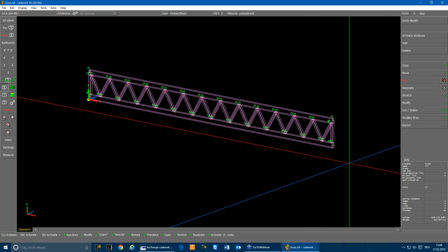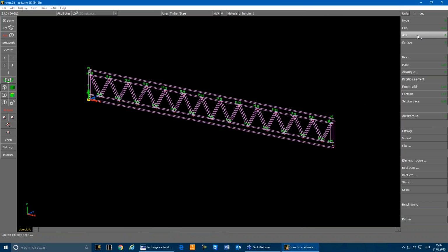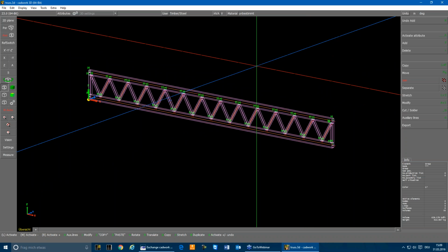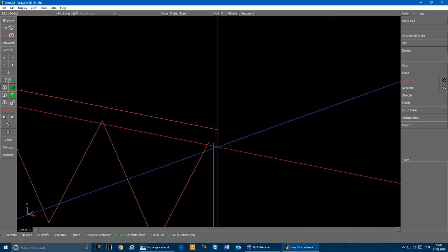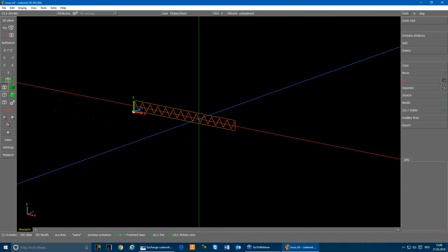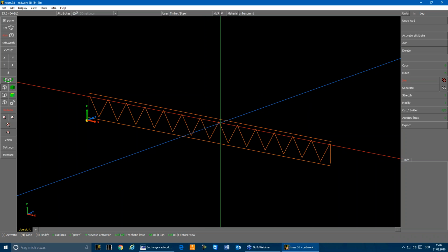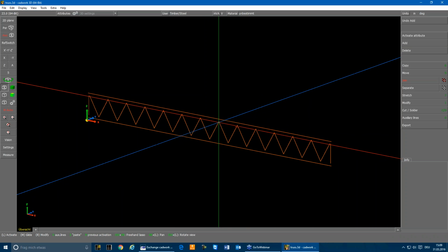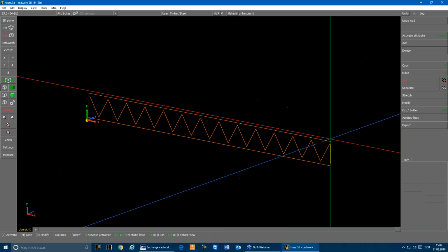The first option is that I will activate all the beams, and I will go to Add Axis and define the system axis for each beam. That means now in the center of gravity of each beam, there is an axis, but you see what is missing here are the eccentricities from this point to this point here.